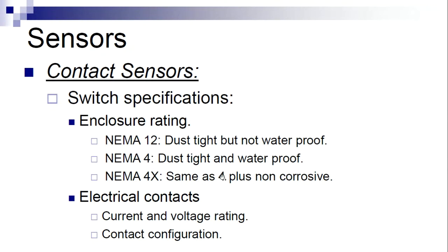All right, so when we talk about these contact sensors especially, and we saw that box on the previous slide, they have what they call enclosure ratings. These enclosure ratings are rated for different types of applications. I just have a couple of them listed here to be aware of. I don't really expect you to memorize that NEMA 12 is dust type but not waterproof, but I just wanted to show you. So NEMA is the national code settings for these.